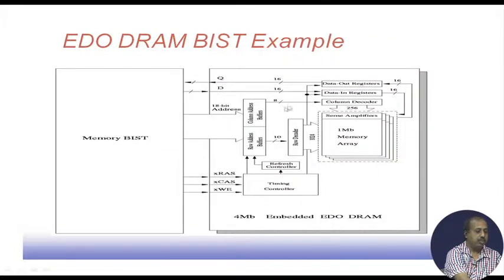This actually shows a DRAM structure. This is the memory array, it has got sense amplifiers and all that, and as we know the memory is arranged in a 2D fashion. So, there will be a row decoder and a column decoder. This has got 1024 rows, each of 256 columns. They will be generating any address that we have. This address has got a row address part and a column address part. The row address part comes to the row decoder, the column address part comes to the column decoder, and they are actually selecting a particular location.